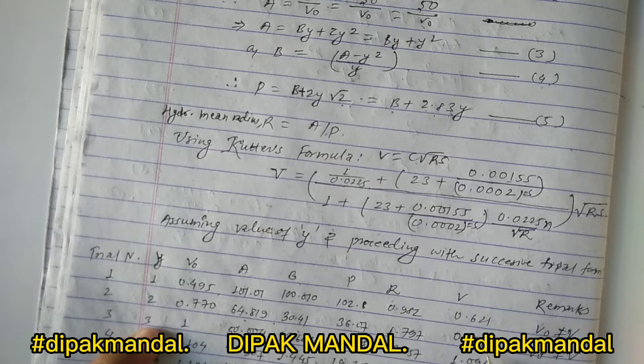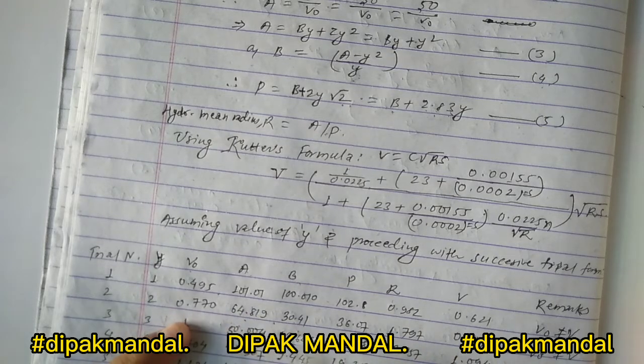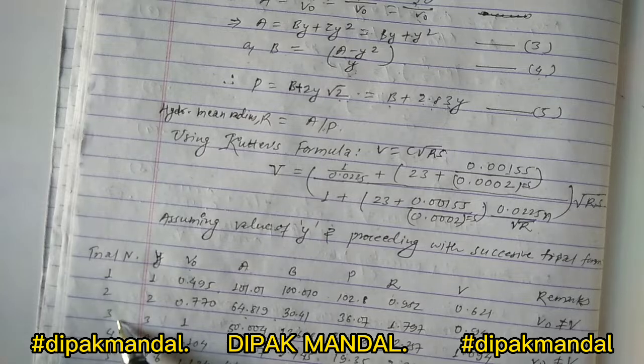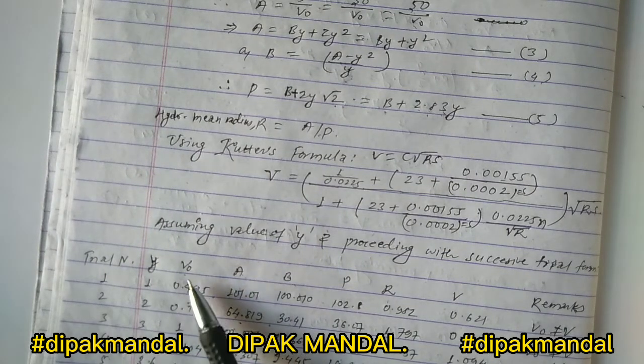Okay, in this way in second trial the actual velocity becomes 0.94. So you can see this is also a very big difference with the critical velocity 0.770, and this becomes 0.94. So we have to perform third trial, and in third trial similarly we take the value of Y equal to 3. Then the value of V naught becomes 1 with the help of above equation.